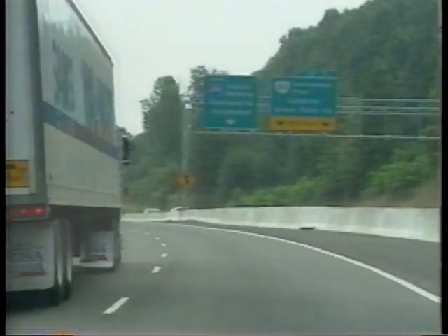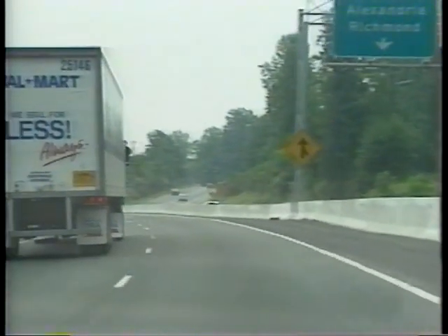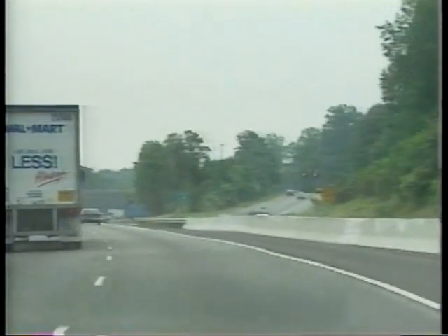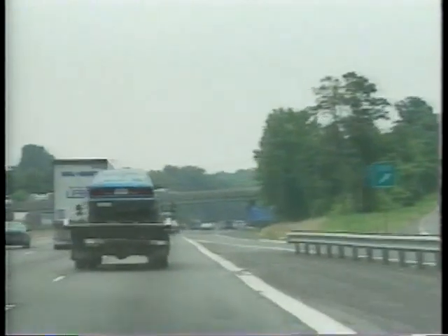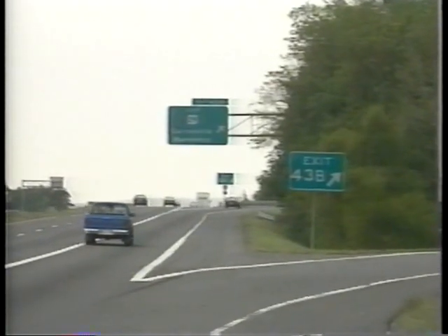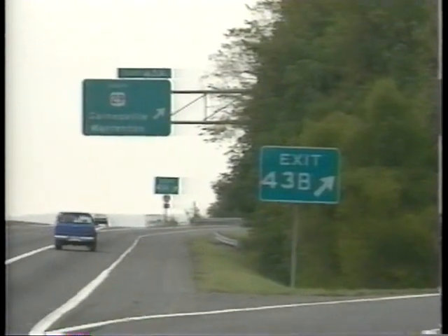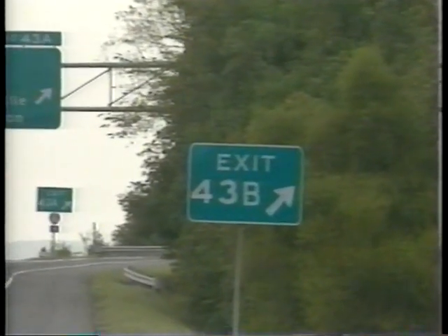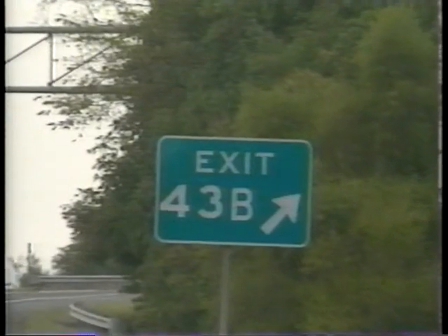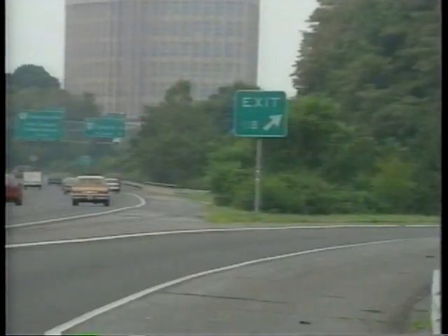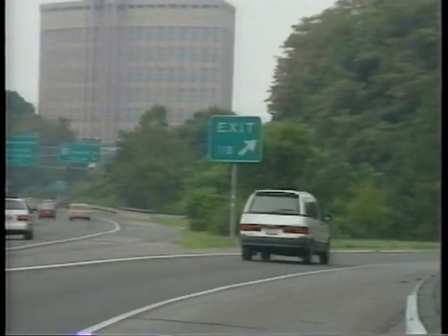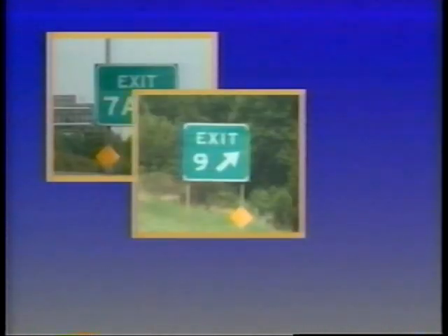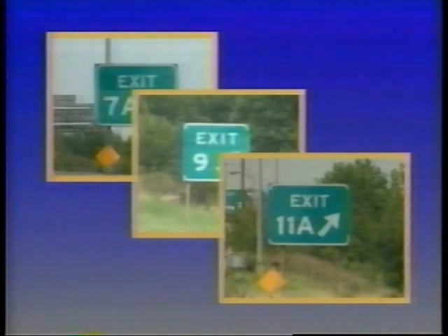Freeways have 4 areas needing signing: non-interchange areas, interchange approaches, interchanges, and service or feeder roads. The gore area at interchanges always has a sign in the area between the main roadway and the ramp. This sign indicates the exit point. All gore areas should be treated the same, so drivers can rely on guide information.